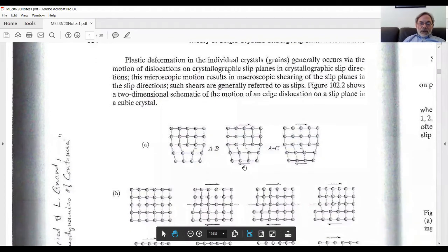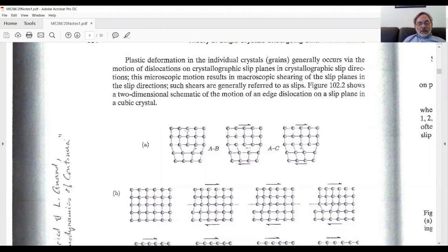So here we have a crystal lattice which is disturbed by a plane of inserted atoms, which we can think of as a defect in the crystal. And this inserted plane has the effect of disturbing the arrangement of the lattice locally. We will call this column of atoms here, this third column, viewed edge on, so it's really a plane of atoms, an edge dislocation.